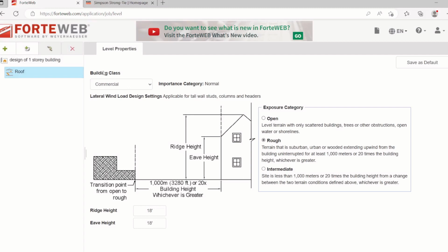Now make sure, like I said in the previous video, that when you open a new level, you have to select this one. Otherwise, you cannot select it. Once you start a design already, like you have a member here, then you cannot select this anymore. So you have to select this one right after you create the level. If it's not residential, just use commercial application.